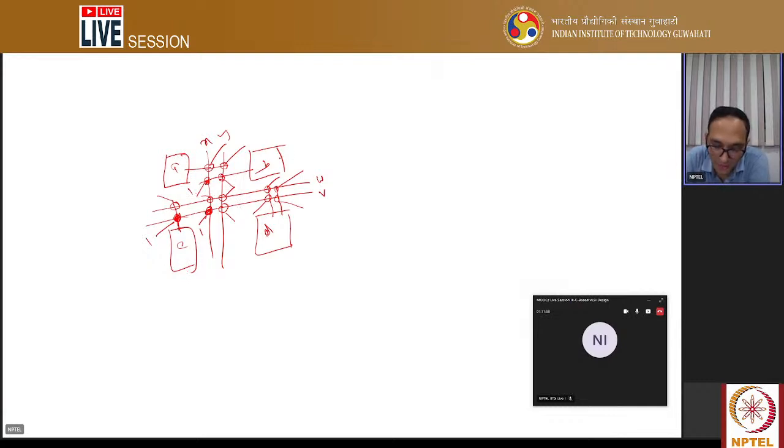So this is kind of configurable in the sense that if you want to make a connection from C to B, you will give 1 to these 3 bits. Now if you want to make a connection from A to D, you will give accordingly. You can give this one 1, then this one 1, and then this one. Then this is effectively a connection from A to D. So this is the reconfiguration, right? Your connections are there already. You are just deciding, based on your application, how to make the connections. So this is the reconfiguration.